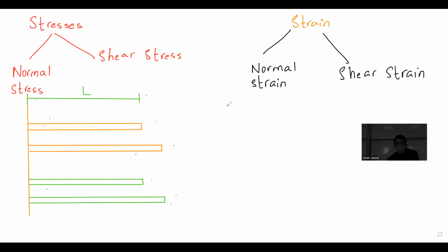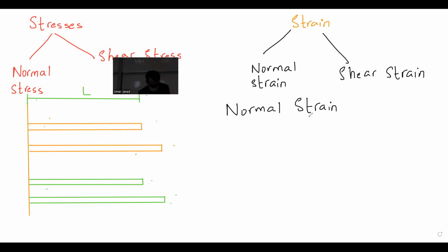Now, what is the definition of normal strain? Anyone from their physics classes probably? Yes, precisely. Longitudinal deformation. I will call it as change in length divided by original length. So remember the word original. The units will be meter per meter or inches by inches. Now your textbook does use these units, which I personally don't use, which is RAD for radian.